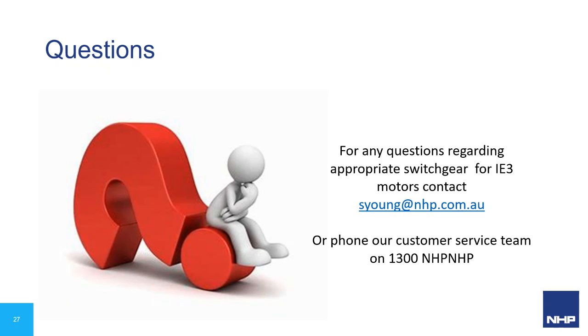I've got one other question come in. In general, do the thermal magnetic circuit breakers have a shorter minimum trip time than the electronic circuit breakers? A shorter minimum trip time, a faster reaction time to a high level short circuit? The answer to that normally is yes. Under high fault conditions, we're not talking about just the standard thermal and magnetic curves. We're talking about levels of short circuit above that which is graphed in their thermal magnetic tracing.